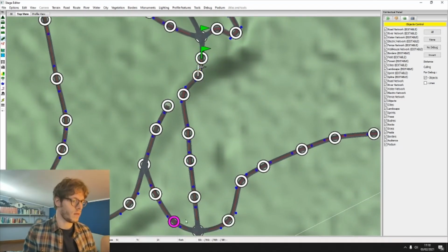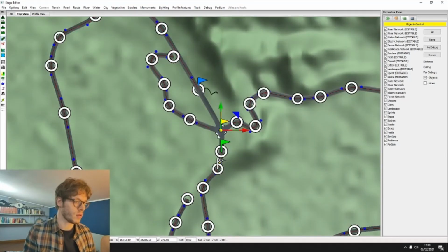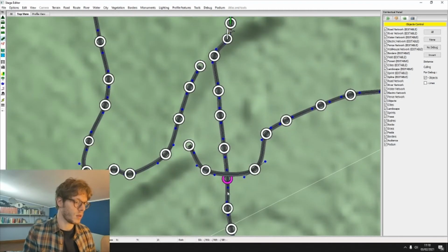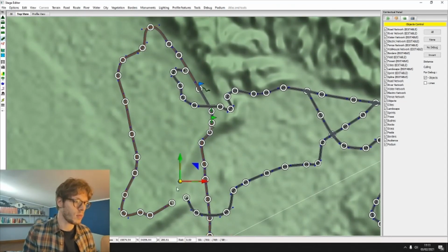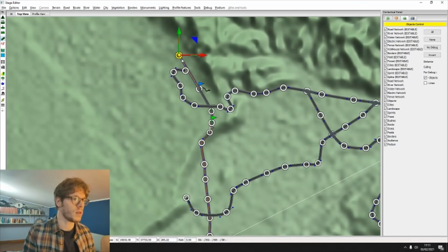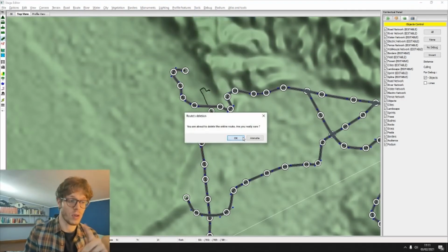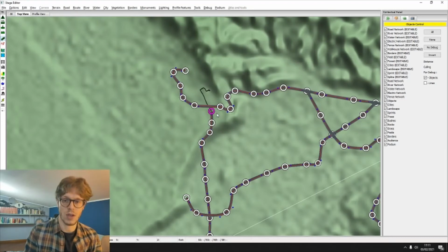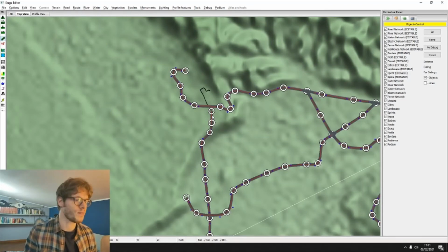So I created something that is a bit circular in this, so I have to modify the road a bit. I complicated the life a bit, sorry for the little mistake. To remove the route, I remove all the route that I created. In this case it's just 2 points, but in this way I created all the route so I can modify the road. If you want to modify the road, you must work without the route, it is better. If not, you can create some bugs in the stage and it's not good.